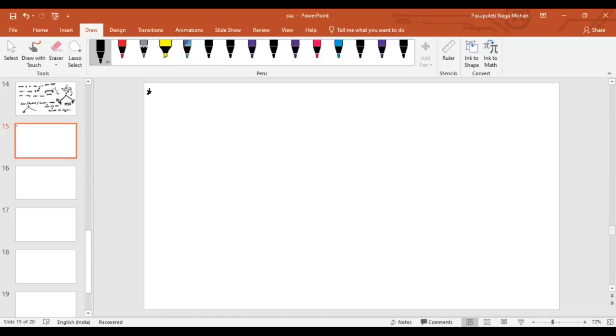The characteristic compressive strength. You substitute FCK in MPa, then only you will get your Young's modulus in MPa. Right? So these things you should know. You have to substitute in MPa, then only you will get MPa. But if you forgot this, and you substitute in another unit, then you are gone.